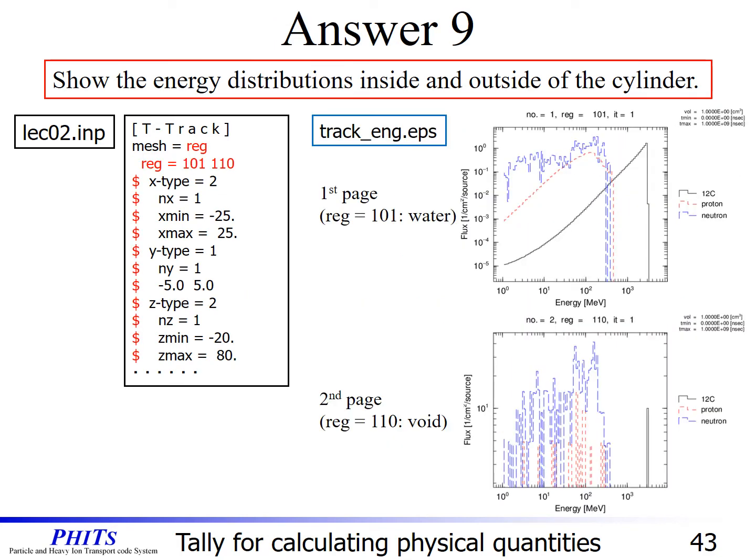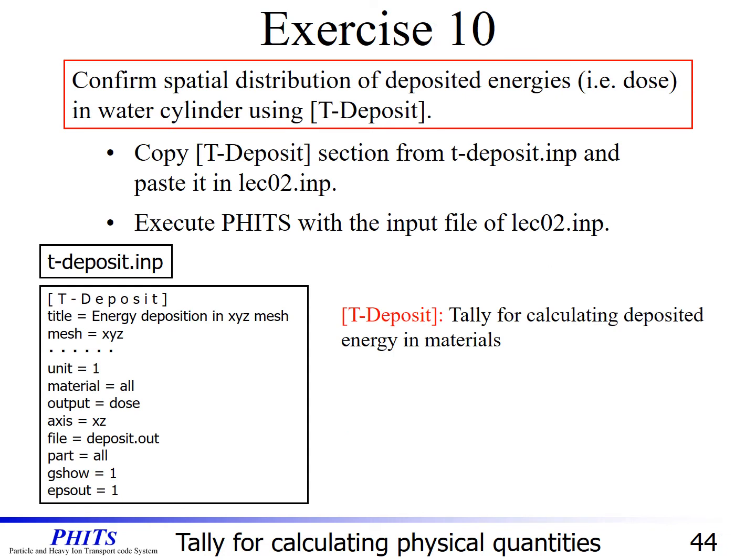Here is shown the result. You can see the energy distributions of each particle inside and outside the cylinder. Let's go on to exercise 10. Here, we will confirm energy deposition using the deposit tally. Please open the tdeposit.inp file, copy the deposit tally section, and paste it into the lec02.inp file. You can paste the deposit tally section wherever you like, except the middle of each section and below the end section. After that, please execute PHITS and open the deposit EPS file.